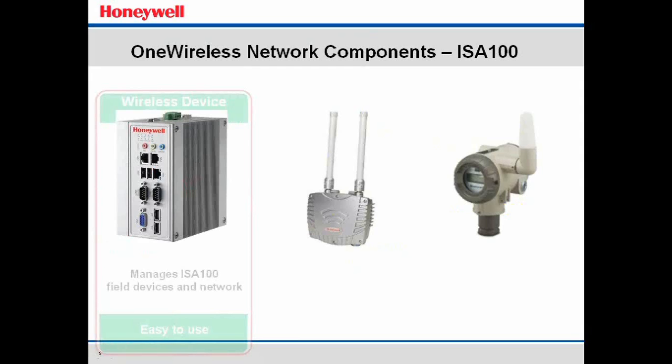And the algorithm recognizes, if you look at the top example, the transmitters only have one path because there's only one FDAP. If there was a non-wired FDAP in that example, they would still only have one path. The algorithm recognizes that there's a single point of failure at the wireless side where it connects to the wire, and it will not allow the transmitters to form up redundant paths because there is a single point of failure in the network. That's a software feature they built in to try to ensure that we always design in redundancy. So the bottom one would be what it should look like.